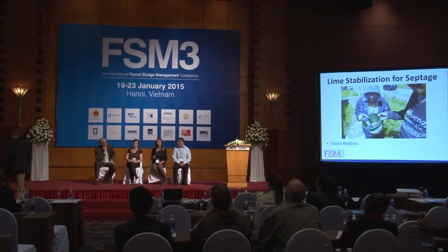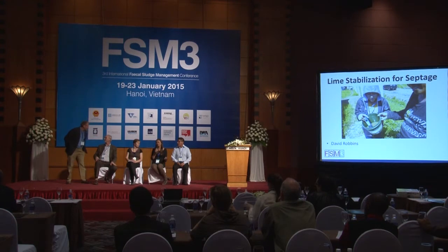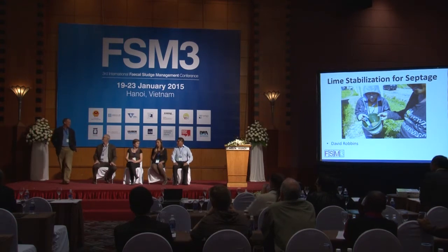So ash would work in a similar way by raising the pH, but it doesn't get it anywhere near the 12, and 12 is the killing zone that we're trying to achieve with lime. Also, in the case of the source of ash, if you're in an area where there isn't a lot of wood burning, or you don't want there to be a lot of wood burning, it could be a limiting supply. So it would be a different application protocol.